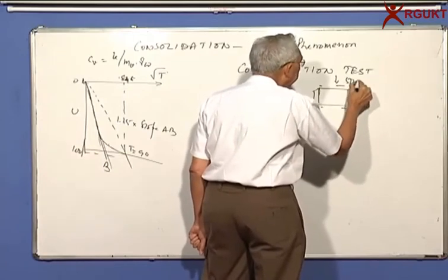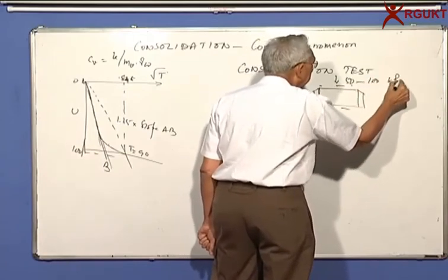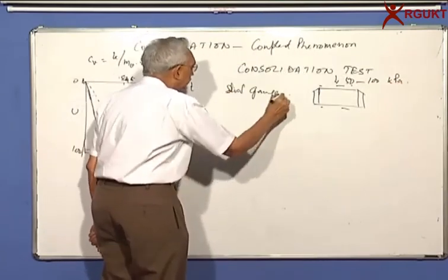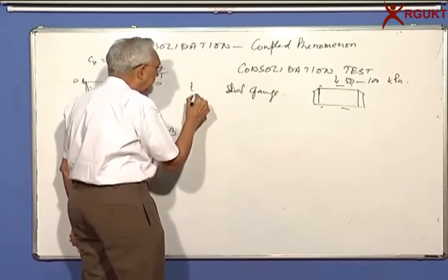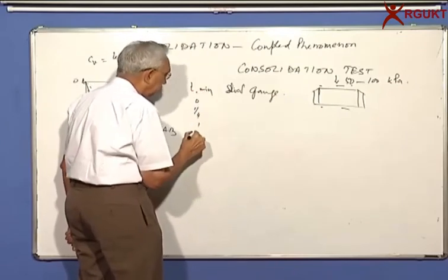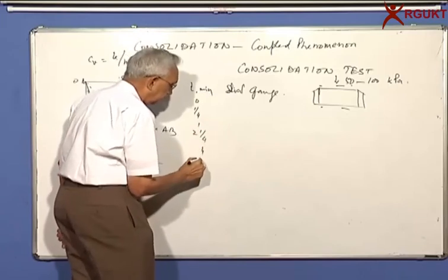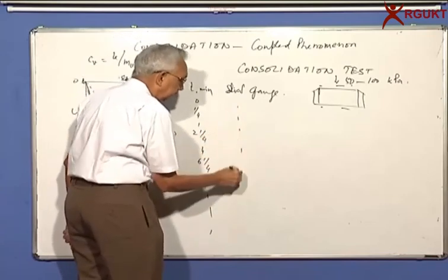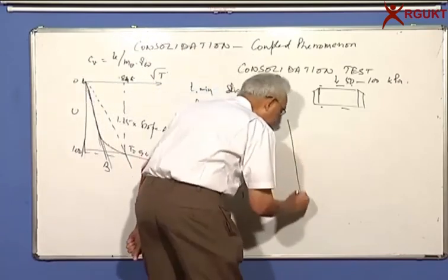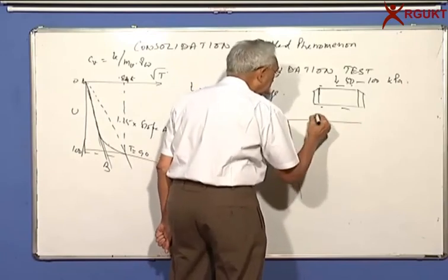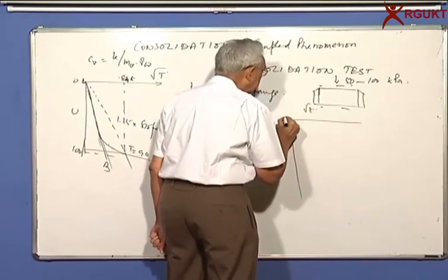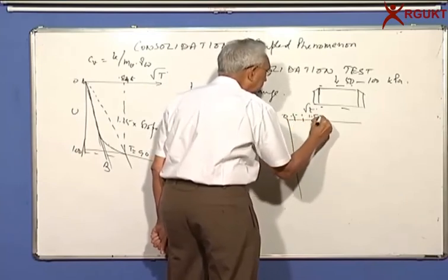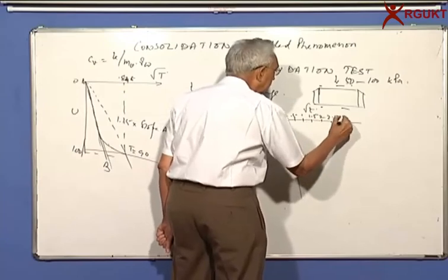Let's say you have increased the load from 50 to 100 kPa. And I take the readings, t and dial gauge reading. So 0, 1/4 minute, t is in minutes, 1, 2 1/4, 4, 6 1/4, 9, etc., for one full day. I have all this. He says plot the square root of time t, which means 0, 0.5, 1, 1.5, 2, 2.5, 3, etc.